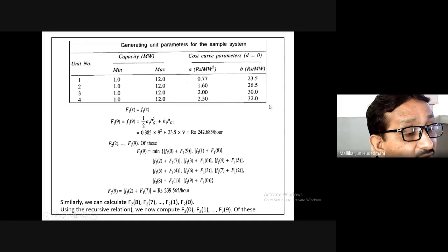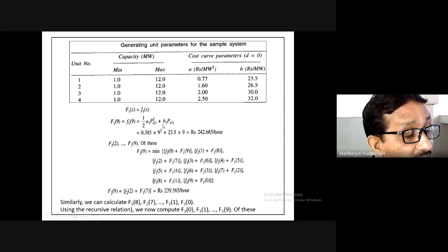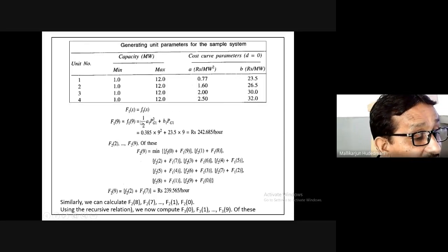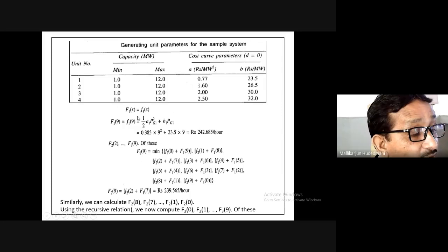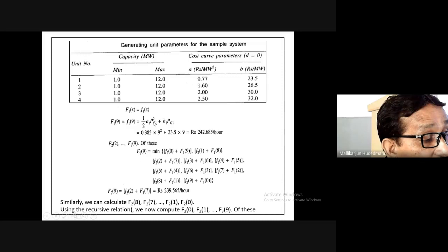Likewise, A4, B4. Okay. Now, for these machines, you have not been given the fuel cost, you have been given the fuel coefficients. You have to obtain an expression as per the table. So the author has directly created this fuel cost function as half A1 PG1 square plus B1 PG1 as the fuel cost format. This is a format.